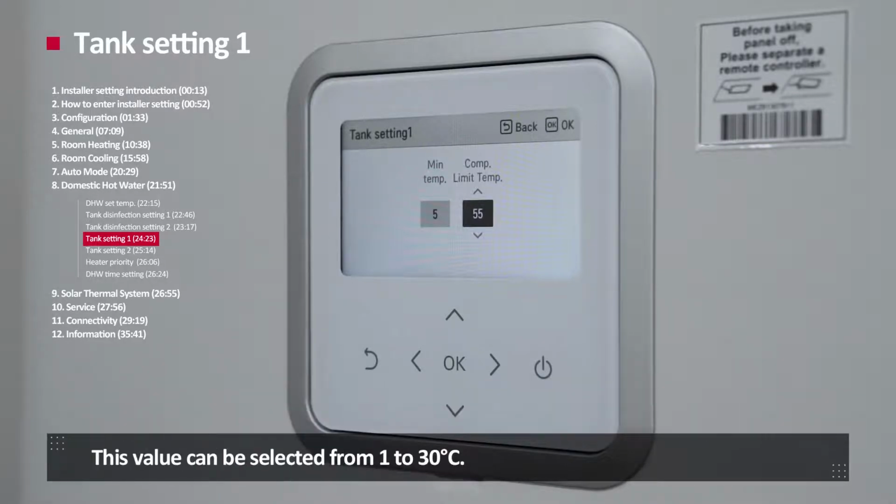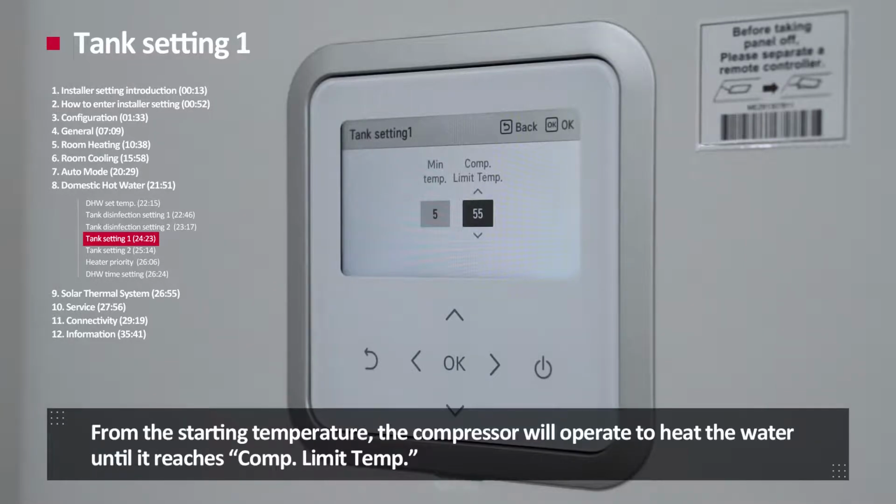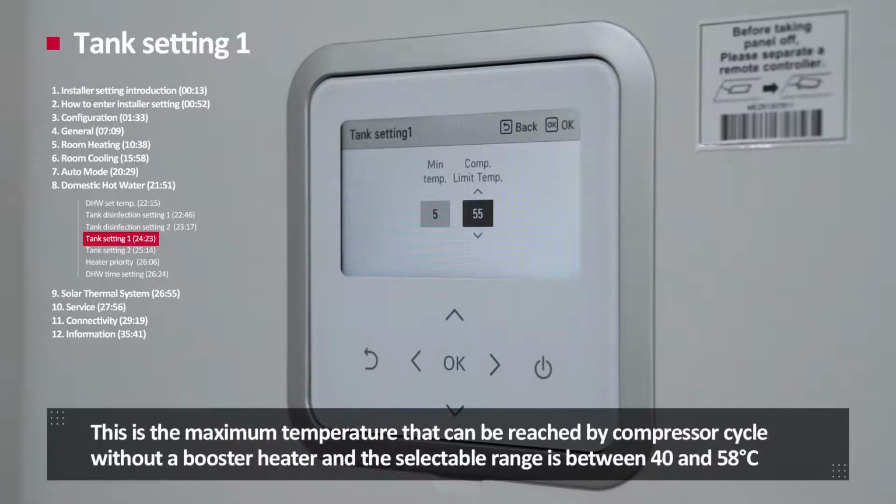This value can be selected from 1 to 30 degrees Celsius. From the starting temperature, the compressor will operate to heat the water until it reaches comp limit temperature. This is the maximum temperature that can be reached by a compressor cycle without a booster heater, and the selectable range is between 40 and 58 degrees Celsius.